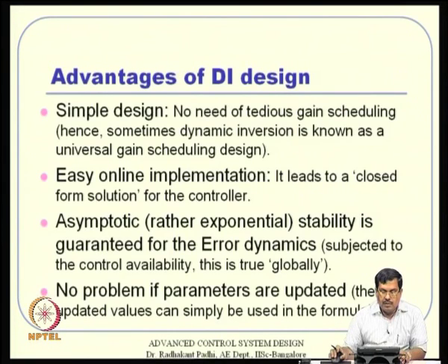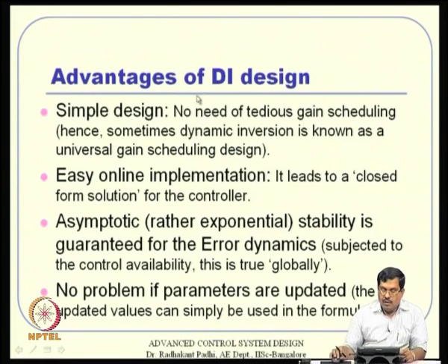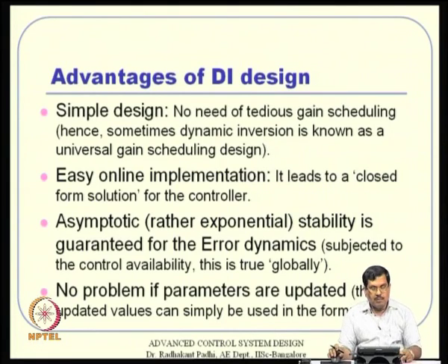All right. Now, what are the advantages, to summarize, of DI design? First of all, it is a very simple design. As far as the understanding of mathematics and other things are concerned, I do not think it requires too much understanding of complicated math to understand why it works. So, it is a much simpler design in my view, and obviously there is no need of tedious gain scheduling, okay, because gain scheduling demands a lot of operating points, and then you design local controllers from linear systems and then interpolate; all these things are not required.